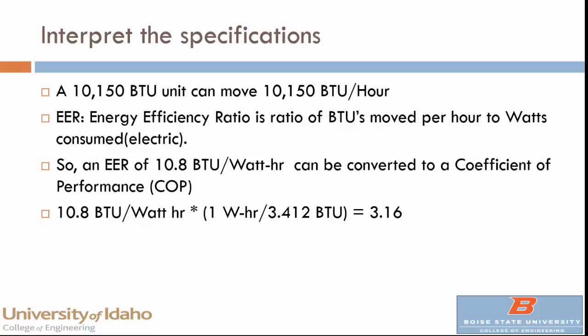Well, 10,150 BTUs doesn't make any sense unless you've got some kind of time associated with it, and in fact all these commercial units say they have the ratings in BTU, but it's really BTU per hour. So it's 10,150 BTUs per hour.